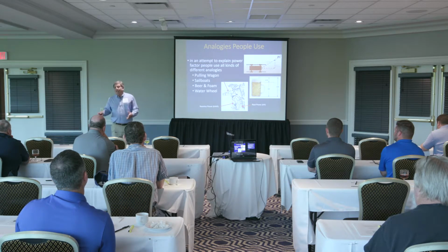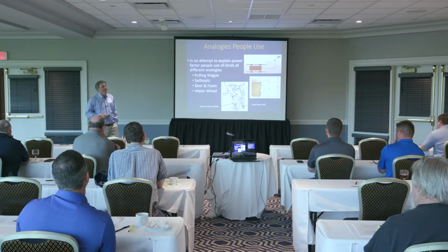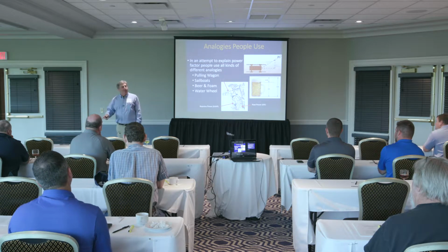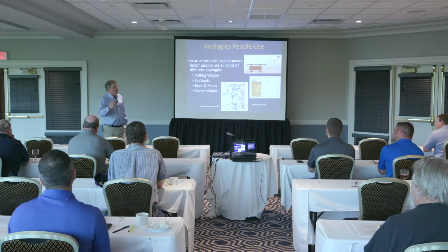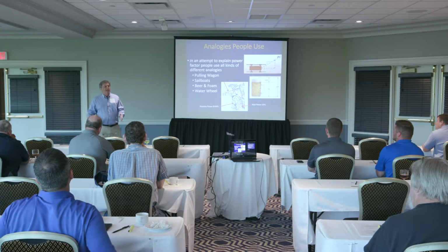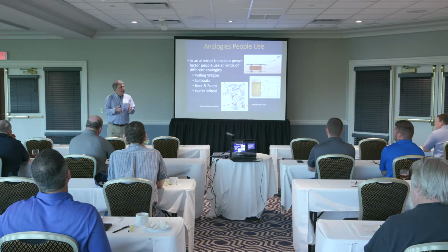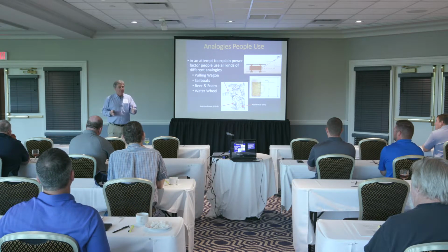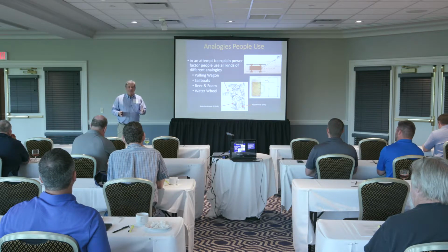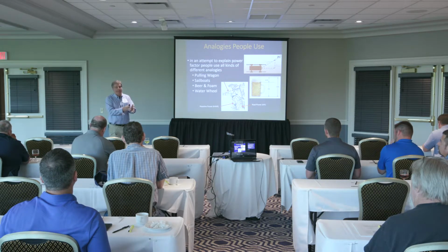So we use all kinds of analogies to try to explain this. I've never found good luck with any of the analogies in terms of getting business people to understand it. But when I go back to business people and I tell them, your motors and your lights and your solenoids in your plant cause the amps from the utility to slow down in relation to the volts, that's the physics. And you can put a capacitor in to speed those amps back up. That's physics.